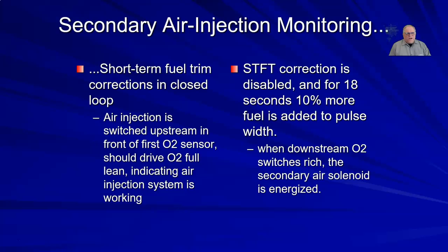Our secondary air injection on the newer cars, all the secondary air systems that I've seen is an electric air pump that's going to pump the air into the exhaust manifold. On a cold engine, we're going to run with a rich air fuel mixture, meaning we're not going to burn all of the fuel that is in the cylinder. By shooting air into the exhaust manifold and having that air in the exhaust manifold when the exhaust valve opens, we'll finish the burn in the exhaust manifold.